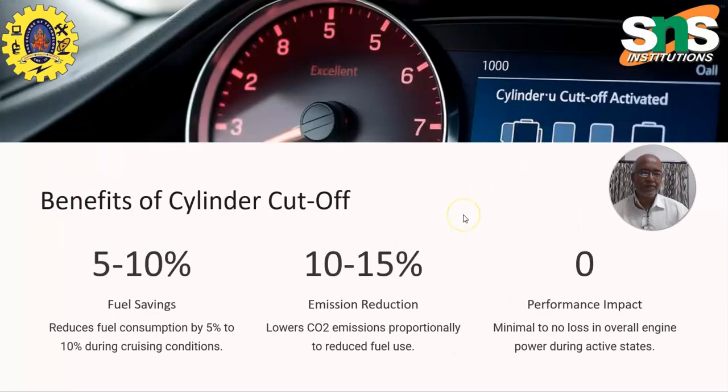Here you can see the benefits of cylinder cutoff technology. It gives 5 to 10% fuel savings, so fuel consumption can be reduced by 5 to 10%. Next is emission reduction. When the fuel is reduced, carbon dioxide emissions are proportionally reduced along with the fuel usage. And finally comes the performance impact, which is minimal to no loss in the overall engine during the activity status.